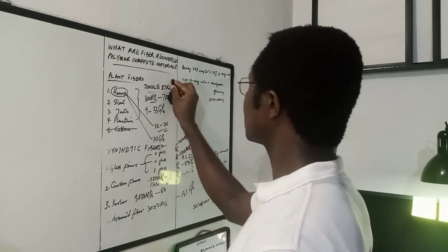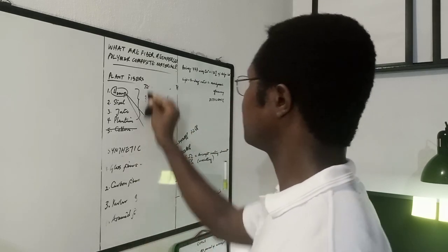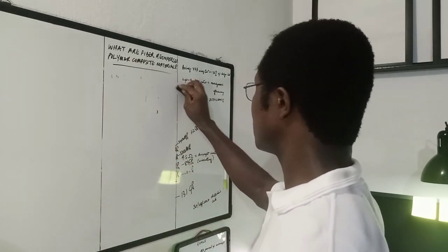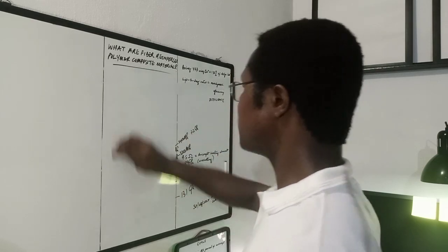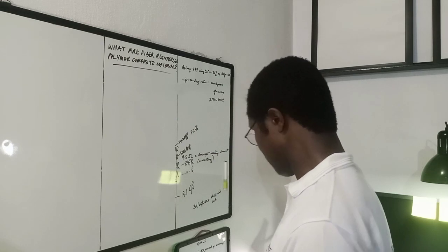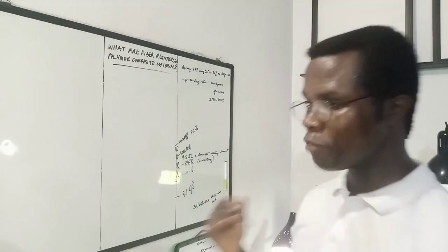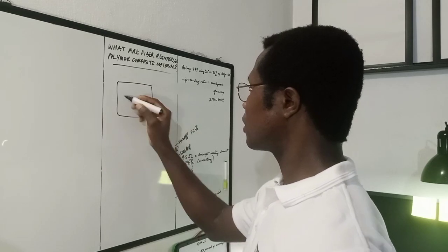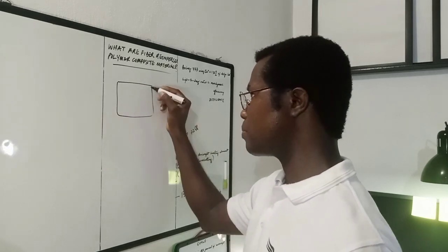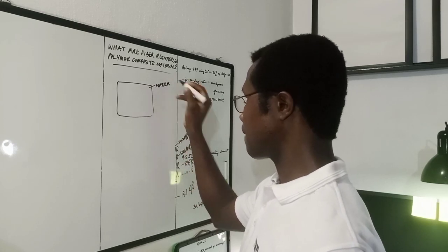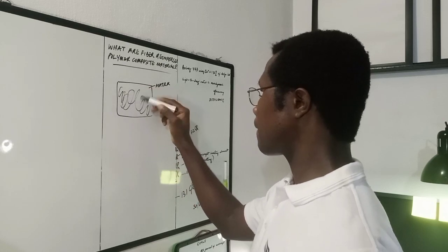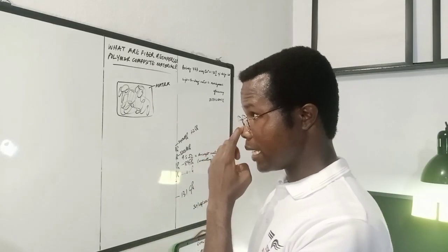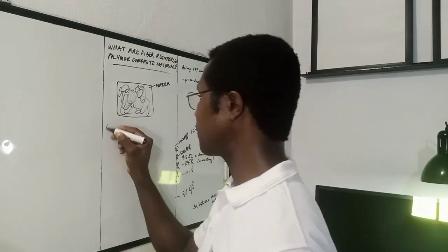Now I talked about what fiber reinforced polymer composites were, and I'm going to very briefly talk about that again. Just to recap, fiber reinforced polymer composites are made when two materials are combined to form a third material. Usually the fibers are combined with a matrix material. So for a composite, you have a binder phase or the matrix, and then you have a fibrous phase, but it doesn't have to be in this particular way. This is a randomly wound up fiber, and that takes me to something called fiber orientation.